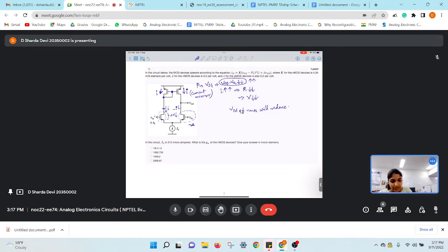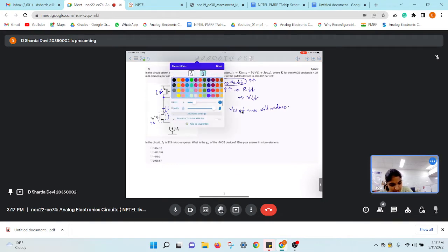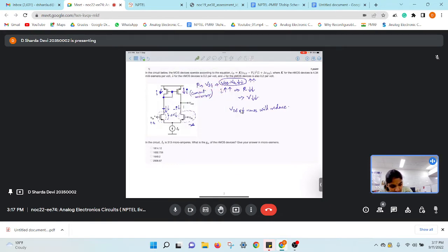If I change the direction to upward, I can change the sign also, so this will be plus i. The above i current and this i will combine and flow into the output, so combinedly we'll get the output as 2i. This will be our I out. This is how a basic OTA works, right?